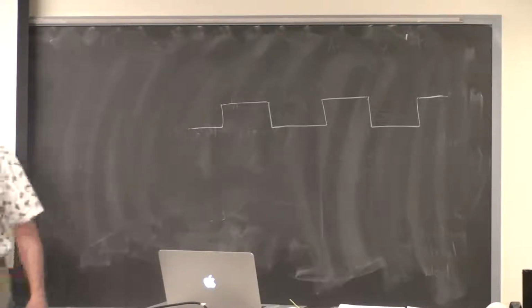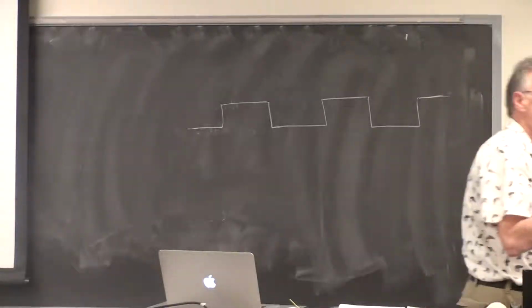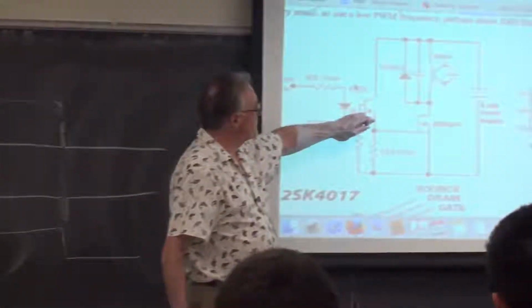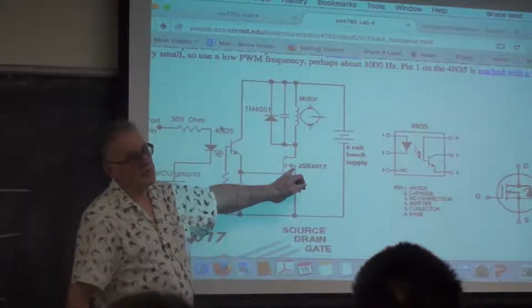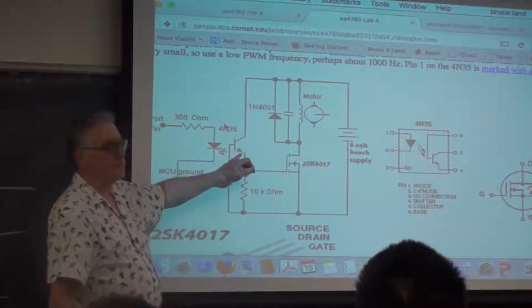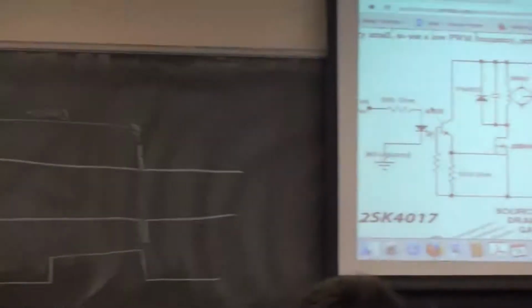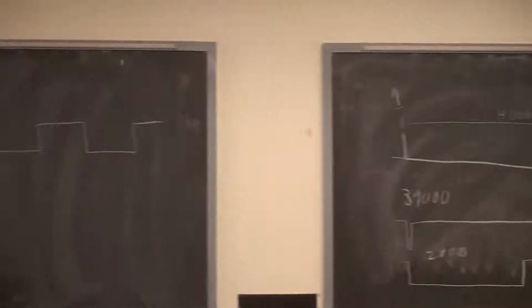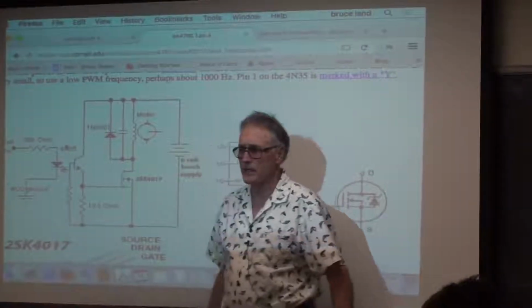So if you were to run the computation faster than that, you would certainly have to use a separate PWM setting interrupt to choose a frequency below a kilohertz for this device. The switch is very fast. The transistor is not fast. The reason it's not fast is that the phototransistor takes a while for charge to leak off of the base.